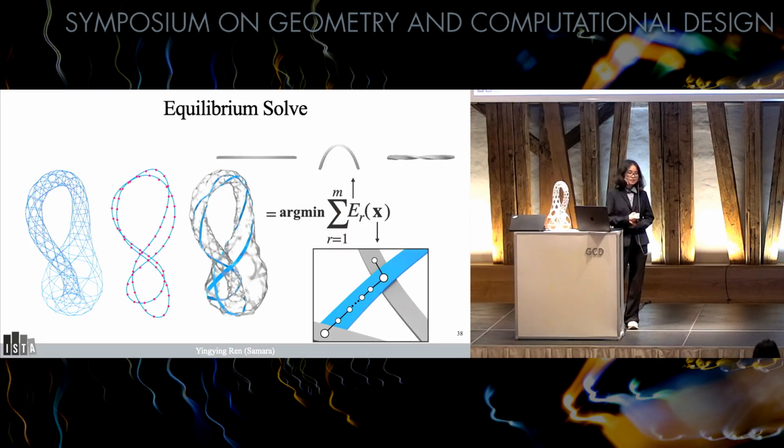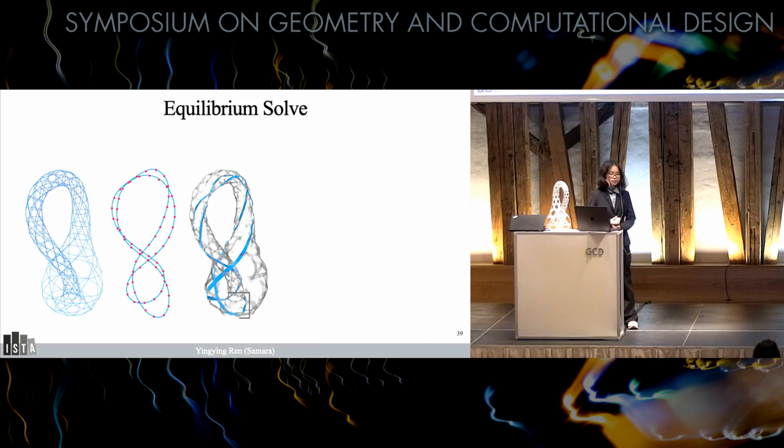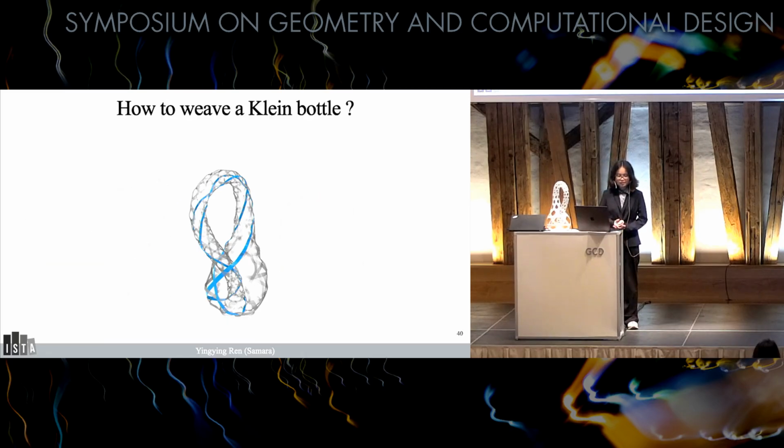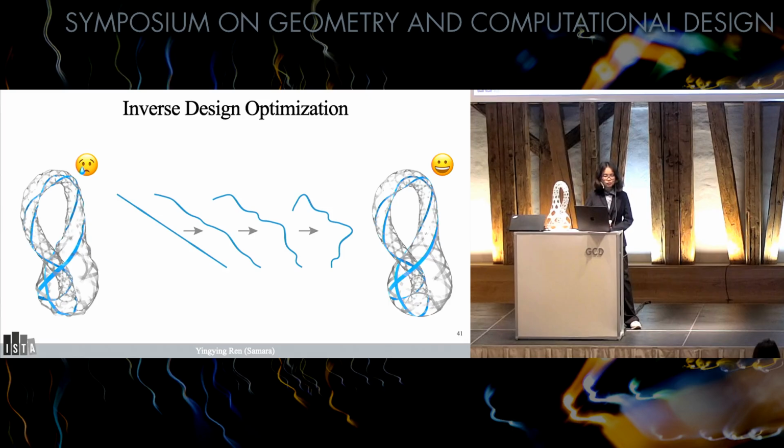Unfortunately, we see that this first structure is not ideal. In particular, the ribbons have lots of twisting and buckling, and the crossings experience high stresses. This is because currently, this topology has no singularity. It's completely regular. All of the ribbons are completely straight, so it really cannot conform to the target 3D curvature. We will now improve this structure by numerically optimizing over curved ribbons.